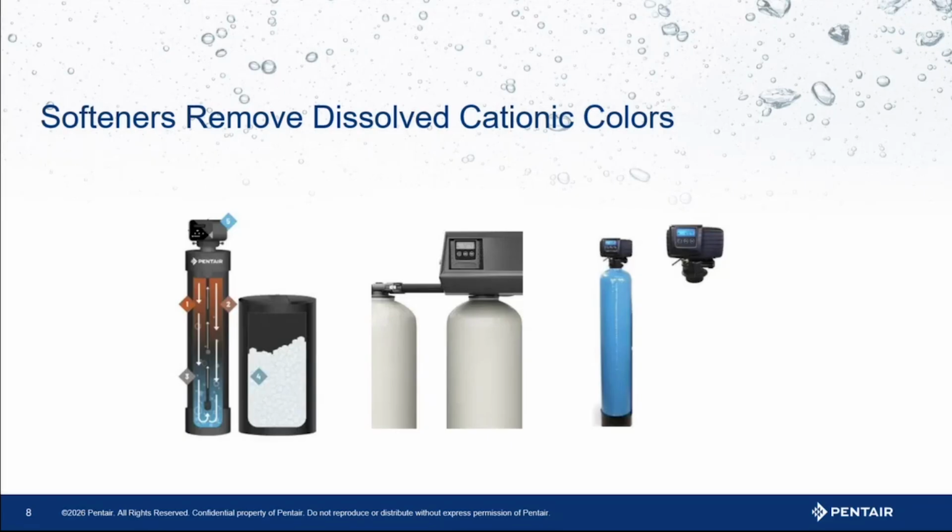So softeners, traditional water softeners using cationic resins, are going to remove cationic colors. Things that are related to iron in the water is very common. You may get a yellowish to brown color. You may get some brownish blackish color from manganese. If you're seeing blues and other odd bright colors, we definitely want our water analysis in those situations, because things outside the rust color spectrum aren't really common in potable water systems.